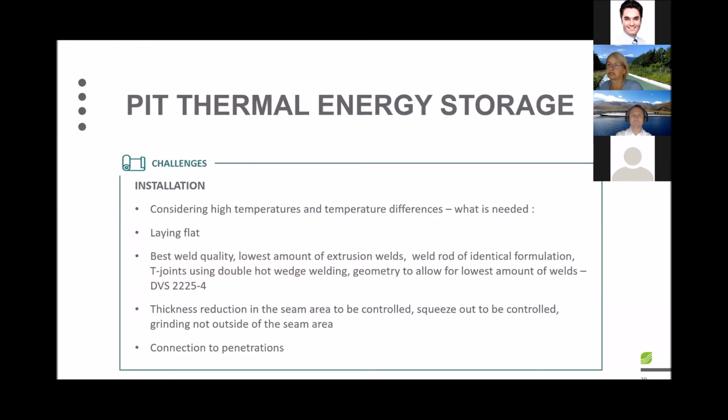What is to be considered during the installation? It is always the high temperature and the temperature differences. It's not only the high temperatures, we have always to address that we have varying temperatures, and thus we shall focus on achieving the best laying flat of the whole application. So therefore it is relevant to have the best weld quality achieved, and to address that the lowest amount of extrusion welds should be executed.